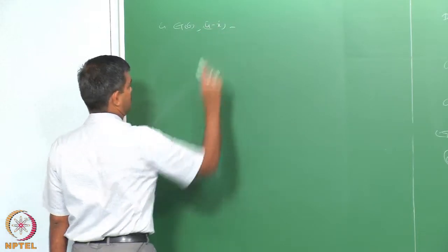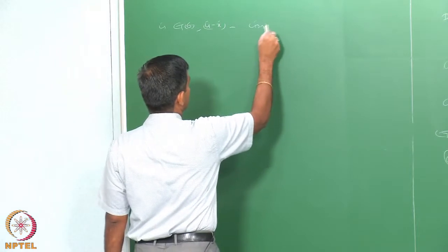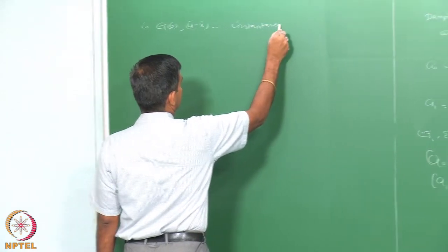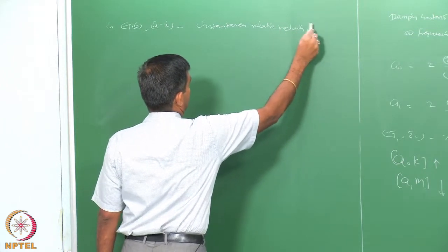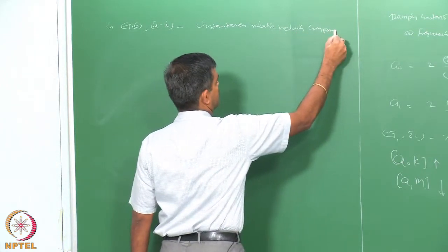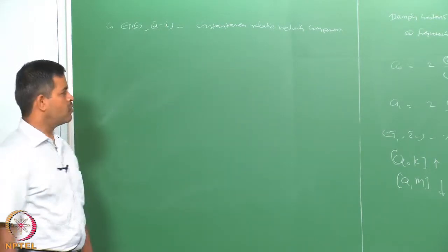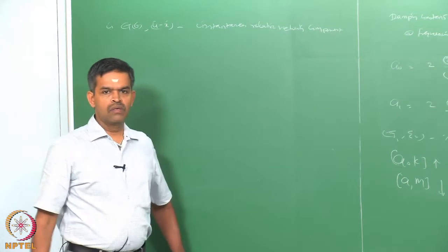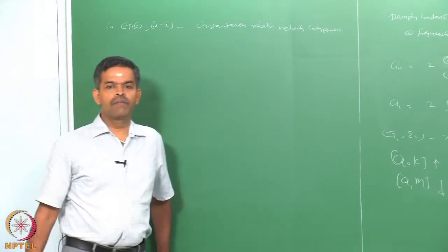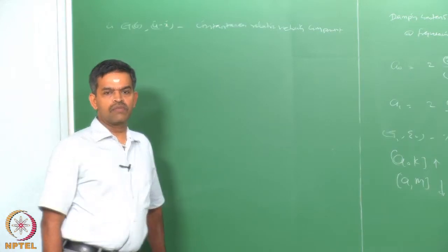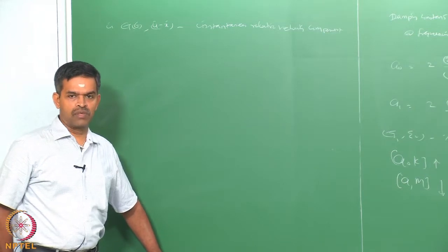So, one can see here in equation 6, u dot minus x dot is the instantaneous relative velocity component between the structure and the water particle. Of course, x dot and x double dot are the structural velocities and acceleration respectively. D is the diameter of the member of the cylinder, rho is the density of seawater, Cd and Cm are the drag and inertia coefficients which are used in the equation.